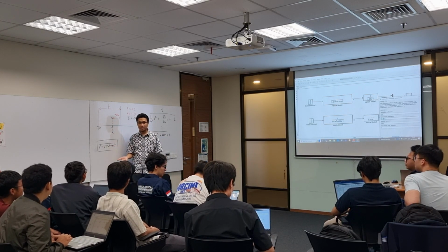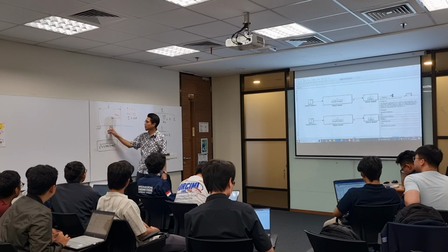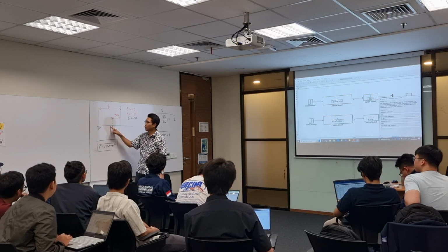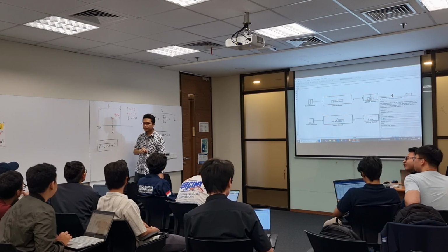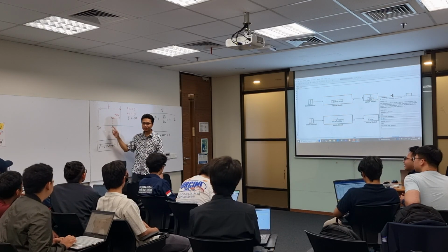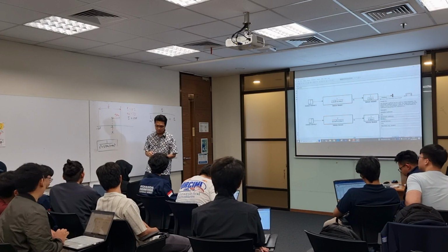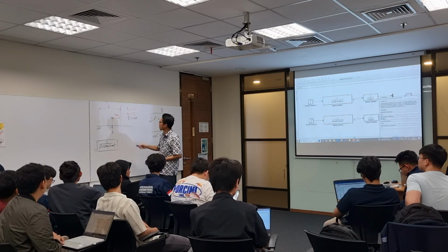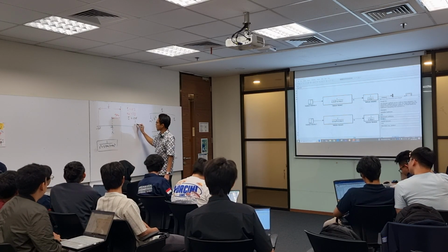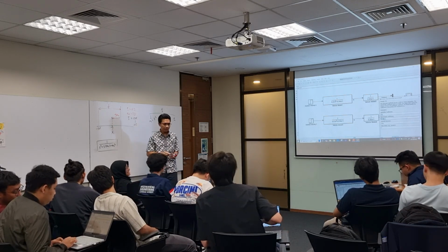You can change it, it's up to you, but keep it close to the zeta omega n. 1/tau is between -20 and -2. So you can adjust the tau from 0.05 up to 0.5, between those numbers.